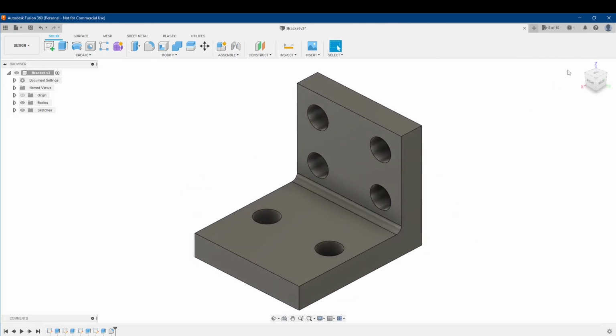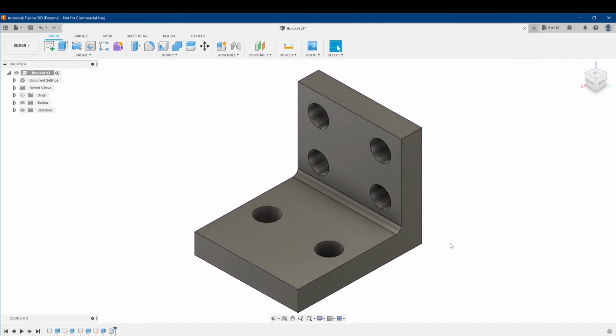Whereas if you printed it regularly, flat on your print bed, your layer lines are going to go right through your fillet, and it's just going to snap at the layer line or shear right there. Because that's what happens with layer lines. They're more susceptible to shear parallel to the layer lines. That's just the way most consumer 3D printers work. Depositing the layers one on top of the other. The bond is a lot weaker there than the continuous streams of plastic that make up those layers.